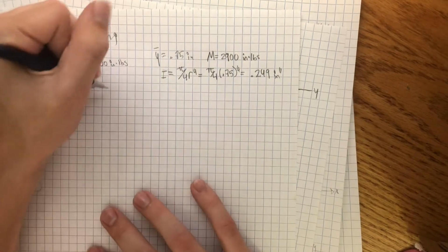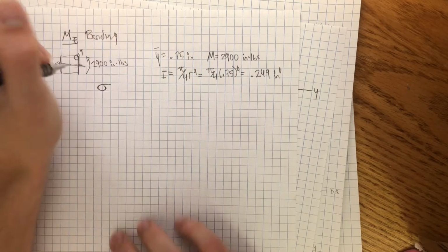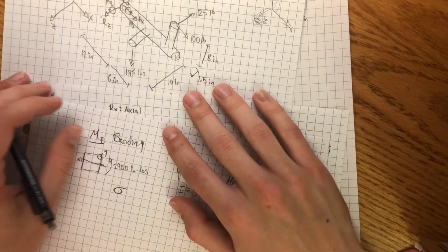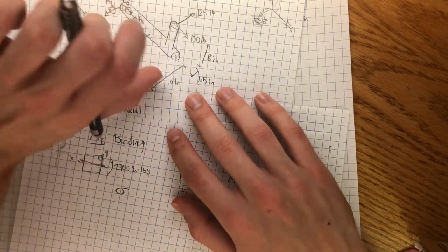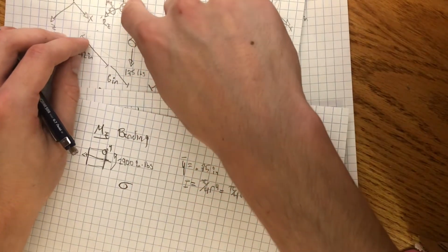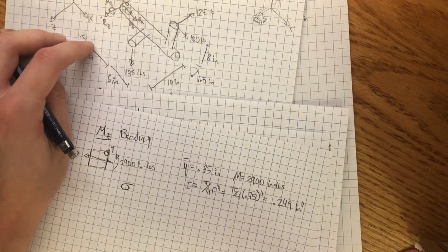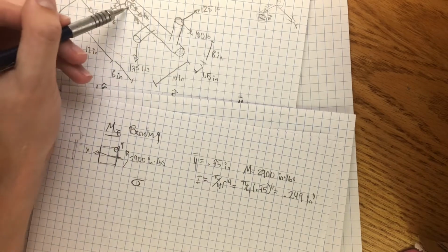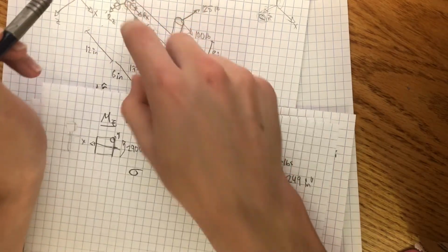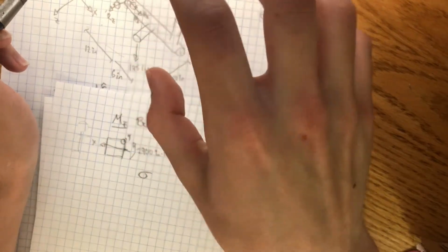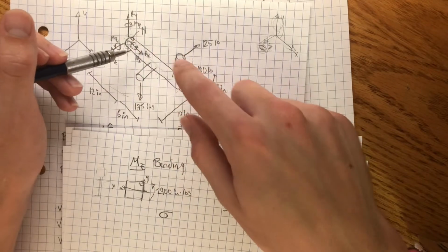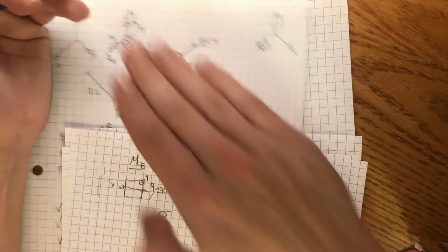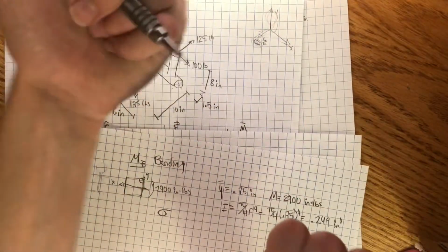So now that we have all that, we can find our stress. So again, this is a stress that would be going in the x direction, because if you look, it would be bending this either down or up, which being that this is actually on one of the outer fibers here, it's going to be experiencing a very large amount of tension or compression, and it's going to be in that x direction because it's either going to be smushing it in like that, or pulling it out like that along that x-axis.